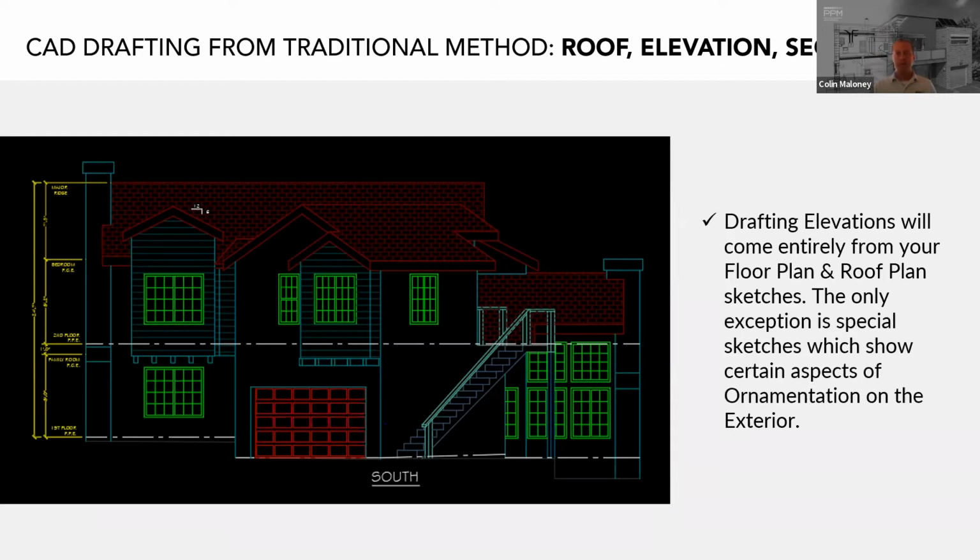Drafting elevations will entail placing all windows and doors correctly with the correct heights. And of course, it's important to ensure they correspond directly with the floor plans in those cases. A lot of people use the pinwheel technique. They'll rotate their floor plan 4 times and drag the lines down. Any decorative items you've sketched and measured can be drafted as well. Drafting a roof in elevation view is one of the most difficult challenges. It needs to correspond perfectly in all other elevation views.